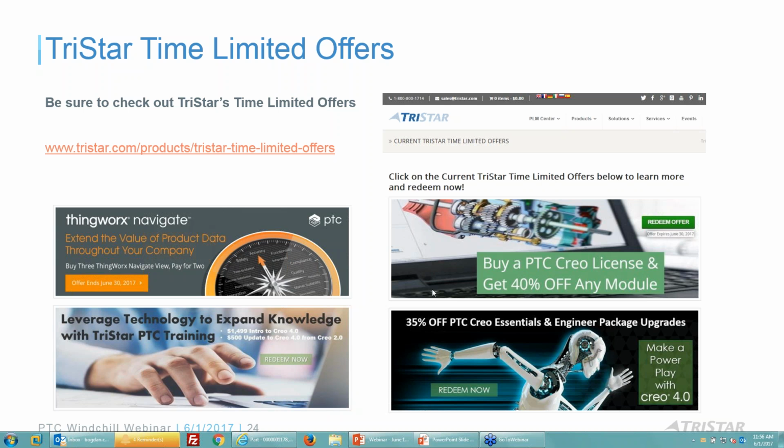There are also PTC University courses on BOM management. They go through the basics of how this works in Windchill, and how the drawing information is propagated into a Windchill BOM. How do I link the BOM balloons to the defined numbers on the BOM in Windchill? That can all be automated when you're checking in the CAD model. So there are some courses on PTC University you could find useful for that information.